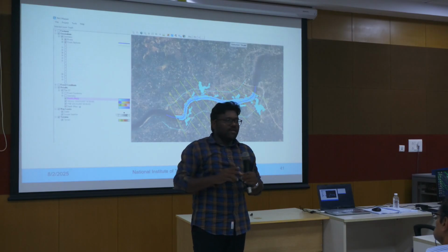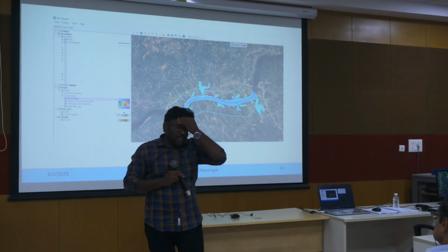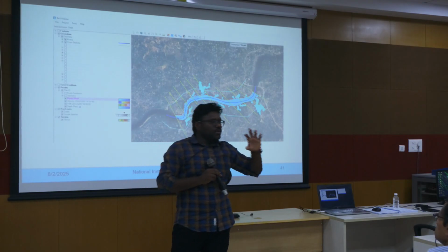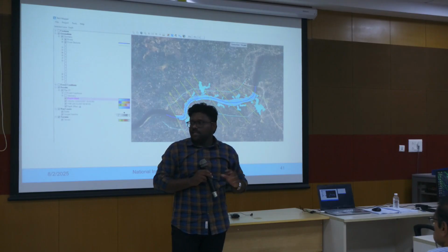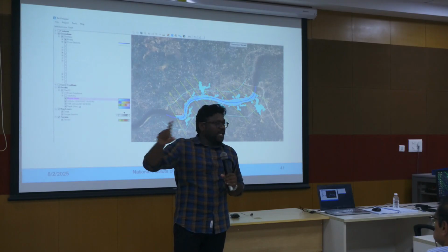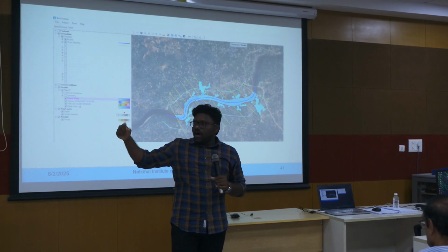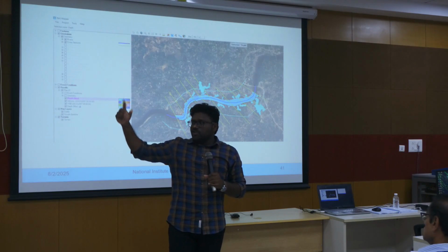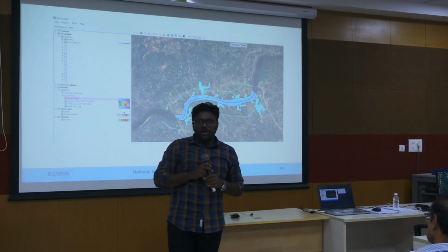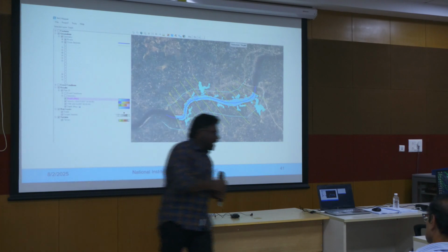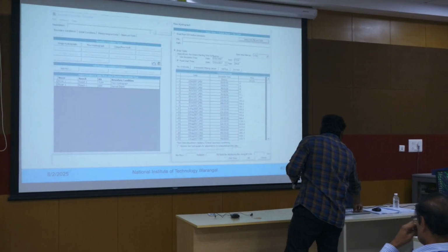So in simple terms, what we can say is like this. Your continuity equation is there, right? So for example, Q equals area times velocity, right? Q equals A times V, where V is velocity. It can be calculated by using Manning's equation, V = (1/n) R^(2/3) S^(1/2). But I'll tell you one thing, like how it calculates. It is important.